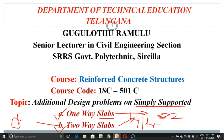Then we have to calculate the effective length. In a one-way slab it is only in one direction, the shorter direction Lx. In two-way slabs, we have to calculate the effective length along the shorter direction as well as the longer direction. Then we have to calculate the total load likely to occur on both slabs, which we can calculate in the same fashion. We calculate dead loads, live loads, given load and finishes, and adding all together we get the total load likely to come on the slabs. If the total load is multiplied by 1.5, we get the factored load.